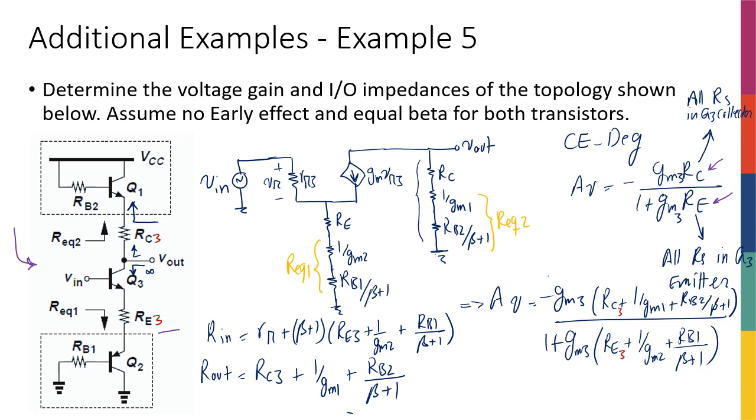Okay, so again, I didn't really need to draw any small signal circuit or anything too complicated, or write any KVLs or KCLs. The only case that we actually did KVL and KCL in this entire chapter was when we were discussing the first circuit, the most basic circuit for common emitter, common collector, common base. We used KVL and KCL, we found the gain for that circuit, and then for every circuit after that, we tried to simplify the circuit to that basic circuit, because we knew the gain, the input and output impedance of that circuit, right? So we tried to simplify everything to that and then see what the relationship between the two is. Sometimes we had to deal with a voltage divider, sometimes even simpler than a voltage divider.